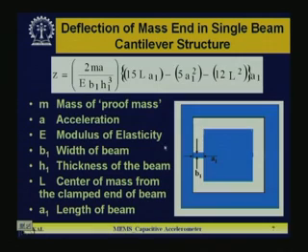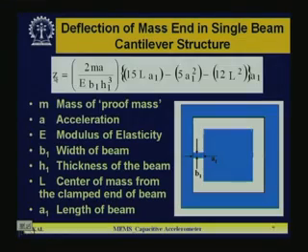Okay. Now, if we know the Z movement of the mass, then we can easily calculate how much the gap changes, because the top and bottom electrodes are fixed. So, if I know the Z, in one case the gap between the two electrodes will be reduced by Z, in the other case the gap will be increased by Z. So, accordingly parallel plate capacitance you can easily calculate. So, that capacitance change also you can easily calculate. Okay. From there you can get the delta C, which is the change of capacitance.